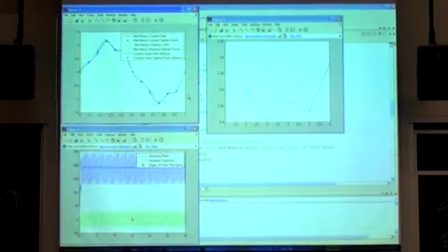That's what I'm talking about, that there's a sweet spot. And you don't necessarily want monotonic increasing. There are limitations on how violent you want it to be in practice, because on a robot, a very violent policy could break your load cell off and almost cost you $400, right? So you don't want to do something crazy. But there's also the willingness that, oh, that's ugly. But you see, if you bounce pretty far, you can also get huge improvements. And so monotonicity in your increasing reward is not necessarily the best way to learn, I suppose. That's from the trenches. I learned that the hard way, many, many hours sitting in front of a machine.